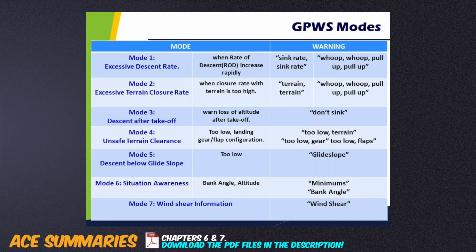Ground Proximity Warning System, GPWS, is a system which takes into account the dangerous circumstances of excessive barometric rate of descent, excessive terrain closure, height loss after takeoff, incorrect gear or flap configuration before landing, below glide slope deviations, approach minima. GPWS uses various inputs to enforce its 6 modes, and works with 2 boundaries per mode, the crossing of which generate alerts. These boundaries are the initial alert boundary and the warning boundary. The warning boundary generates visual and oral alerts.